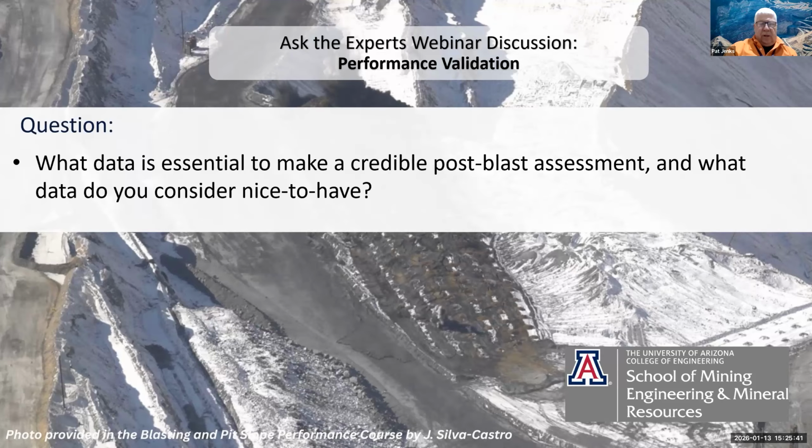I just echo Phil's last point about the validation piece of that, and having adequate seismo data to assess your performance. As he pointed out, that's a key piece of data that often gets overlooked or skipped because we don't have enough personnel to do it or to manage the data that comes from it. But it is really a critical aspect of assessing the slope performance as well as the blast performance. Yeah, great point.